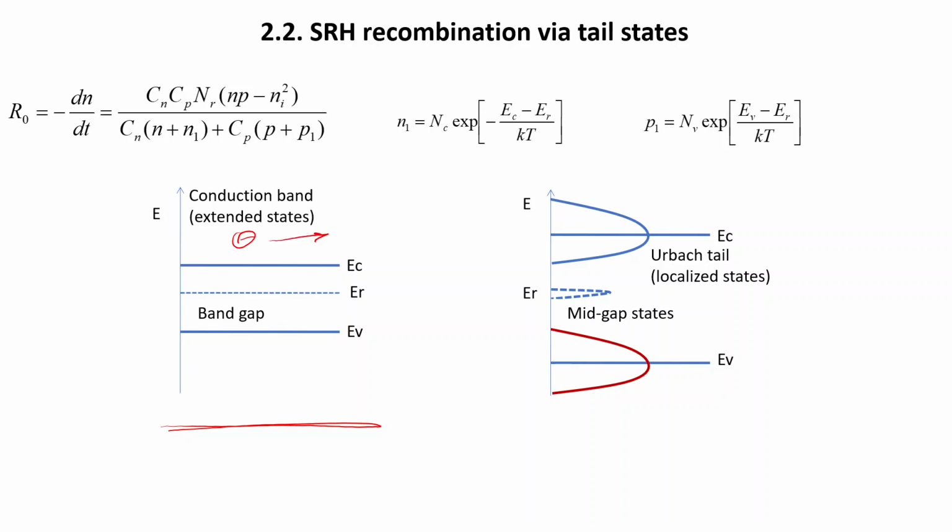In a disordered semiconductor, amorphous or organic, these tails consist of localized states placed close to each other, and electrons cannot just move easily because these states are localized. So there is a hopping mechanism. They can jump from one localized energy level to another located close to them.